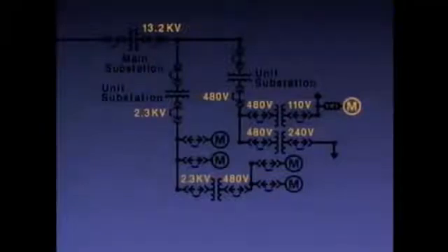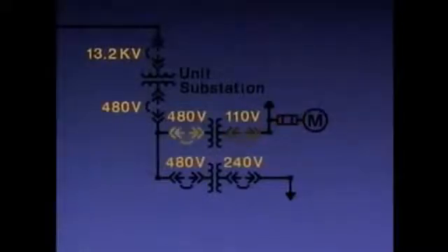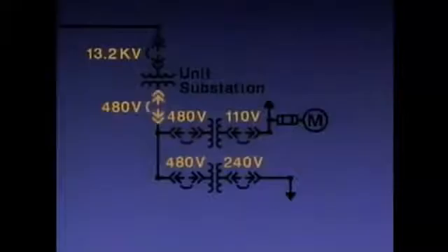After ruling out any mechanical or electrical causes at the motor, you can use the diagram to investigate possible causes in the system. Now, there are different ways to troubleshoot a problem. One way is to check the fuses and circuit breakers to see if a fuse blew or if a circuit breaker tripped. The diagram helps the operator determine where the fuses and circuit breakers are for a particular system. By working backwards from the motor, it's possible to figure out where the power is being interrupted.